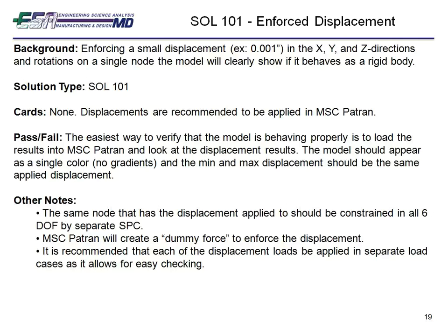If you look at your analysis deck that's written out by Patran, you'll see that Patran is creating a dummy force to actually solve the model for the enforced displacement. And it is recommended that you apply each of these displacement loads in a separate load case for easy verification.